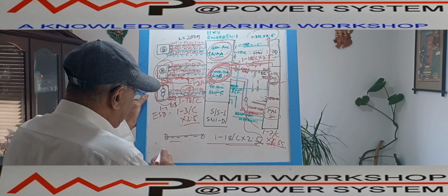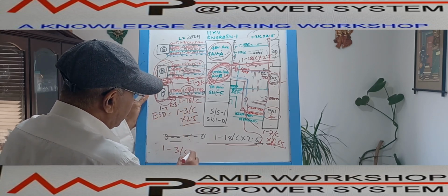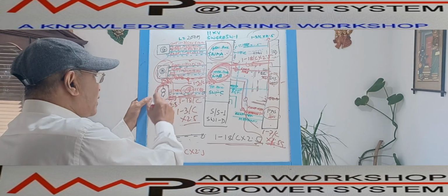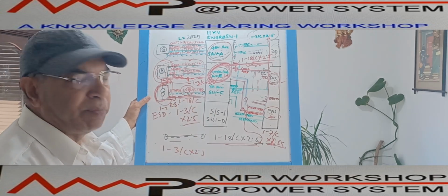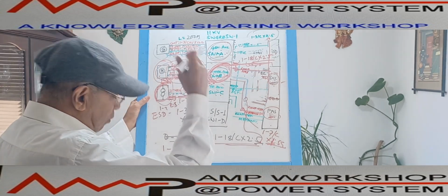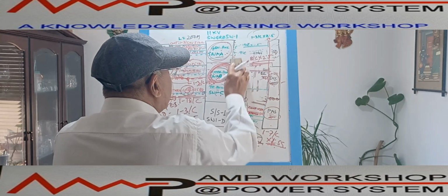That cable will be 1 3-core into 2.5 square millimeter, and the status. From the transformer skid we do not control the circuit breaker. Okay, so these are the transformer cables. And for the control purpose, the same thing, we can delete this part.